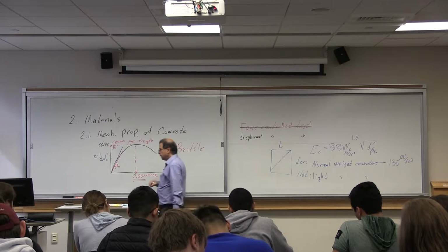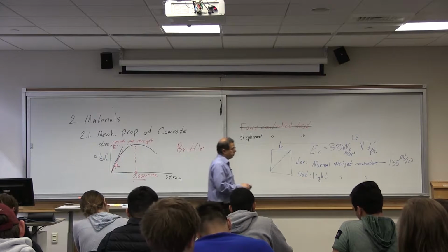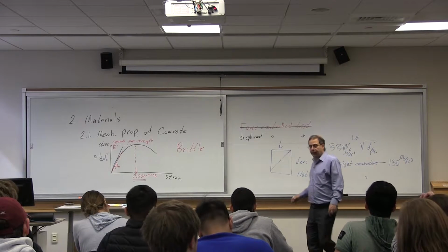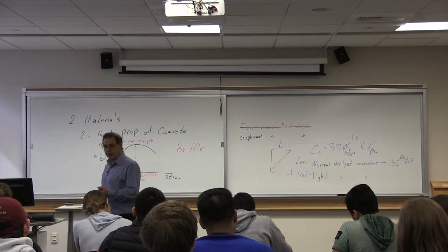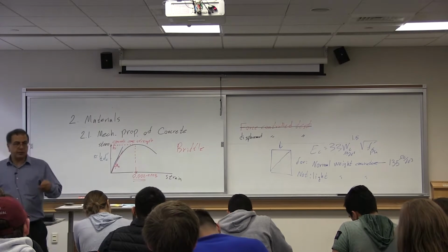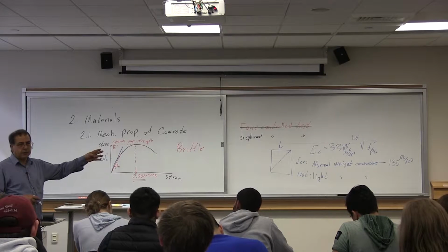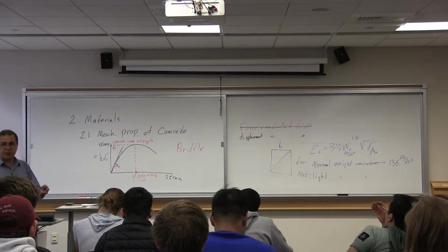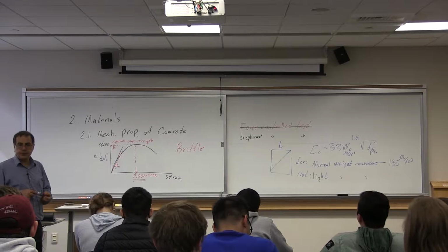When we add rebars to concrete, it becomes reinforced concrete, when you have buildings made of concrete elements, they are reinforced. Reinforcement is heavier. Usually when you look at reinforced concrete, we increase this 135 to a slightly larger number. A round number to remember, a conservative number, is 150.